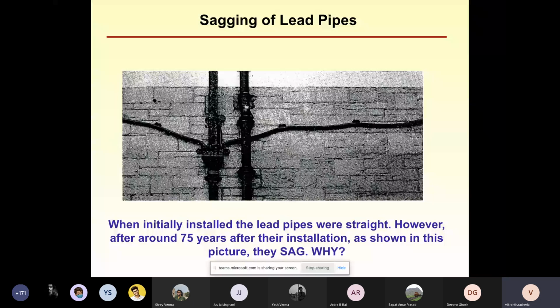Now, for plastic parts, even at room temperature, you have to pay a lot of attention. Why is that so? Low melting point of plastic. If you are using thermoplastics, they have their melting point at about 150 to 200 degrees Celsius. So room temperature will be about 0.55 to 0.6 of the melting point in Kelvin.